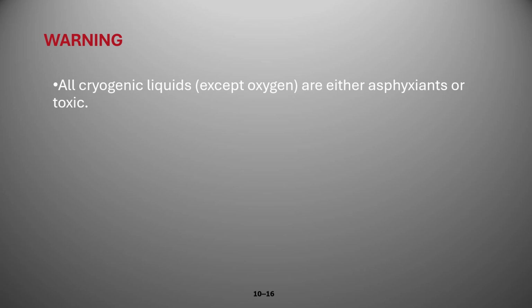And keep in mind, with the exception of oxygen, all cryogenic liquids are either asphyxiants or toxic. So, as inspectors, when we start doing our evaluation, keep in mind that if the nature of the liquid is hazardous to an occupant, think about the increased volume, because it is in its liquefied state.